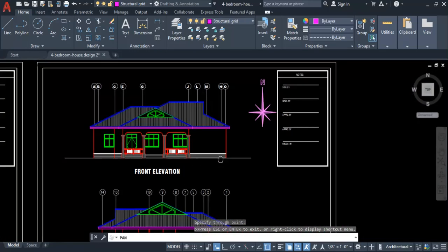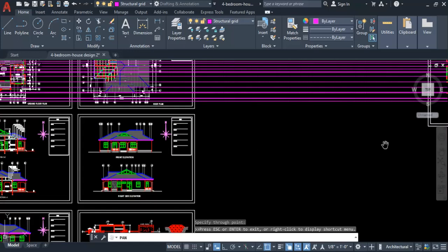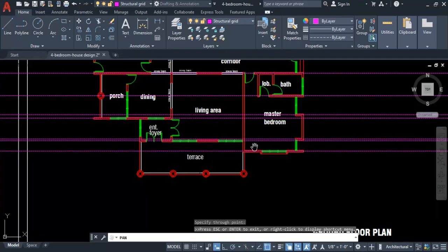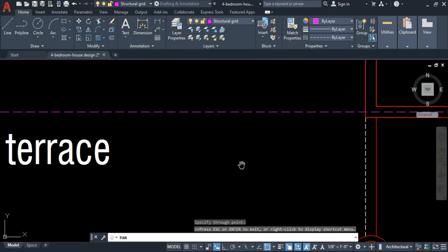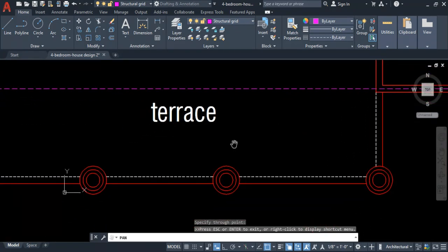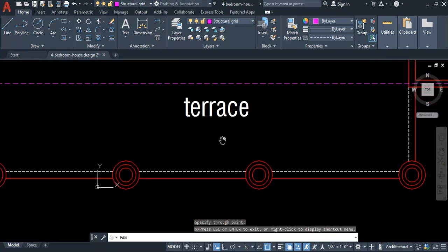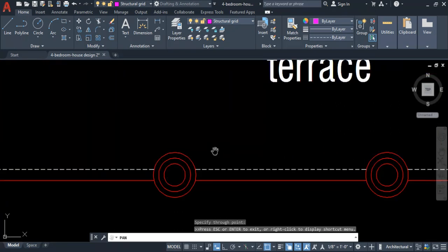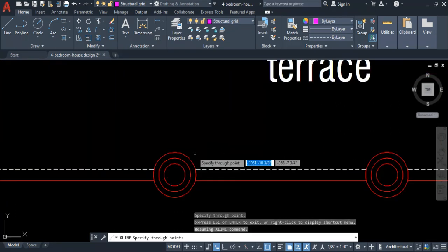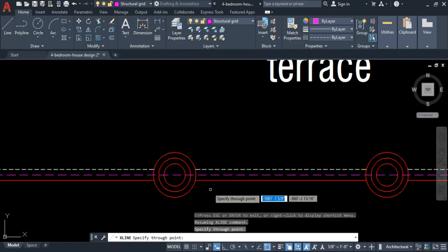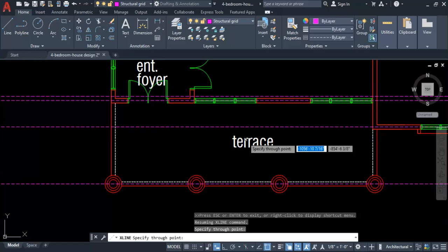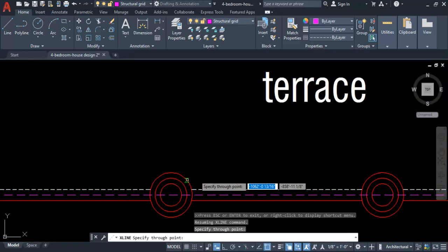Okay, so you also need to take this into account. So what we are going to do, we are also going to place the horizontal grid, since we are also going to be taking this circular column into account. So we are going to place in the horizontal structural grid. So this is the column here. We can delete this interior side column. So you just find the midpoint. This is the midpoint. Then you click on this. Okay. So now we finish placing the horizontal grid.